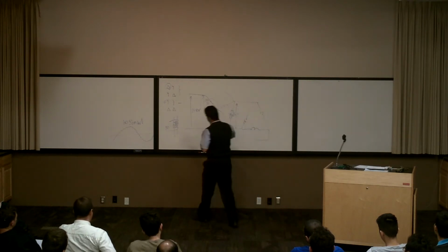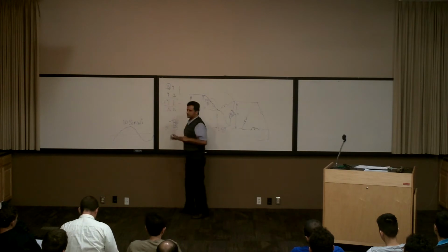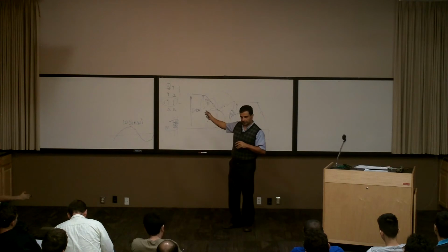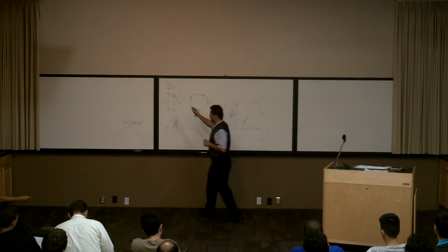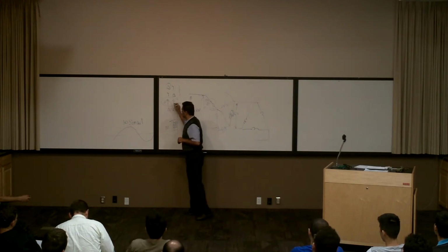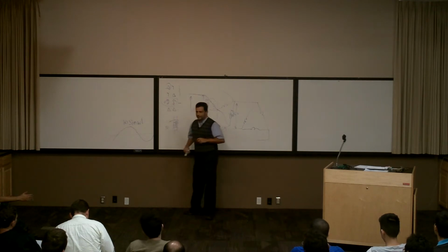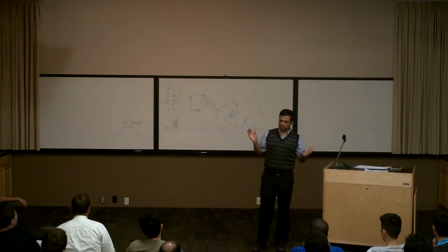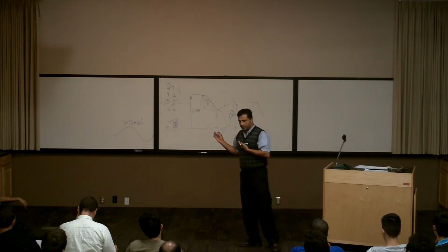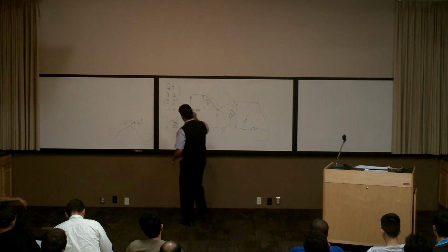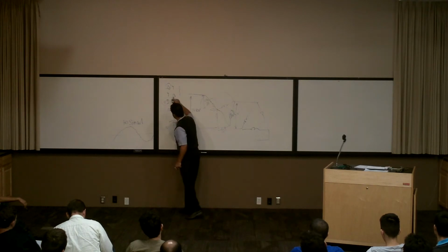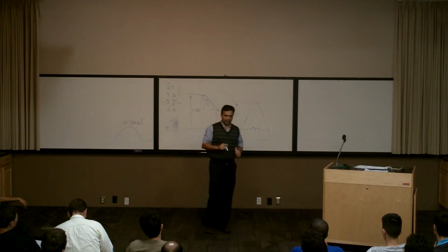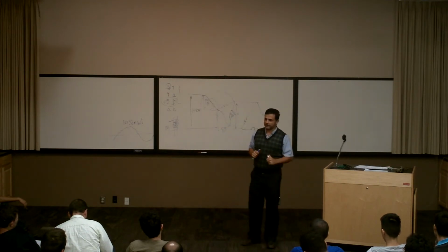Where do we use YY? As you can see, this is like three single-phase transformers, this one with this one with this one. This is good when you have an unsymmetrical load. You have three different loads, you can use this one, and you don't saturate it. This one is going to work with this one, this one with this one, and this one with this one. Sometimes you have an unsymmetrical load, and it prevents the saturation.